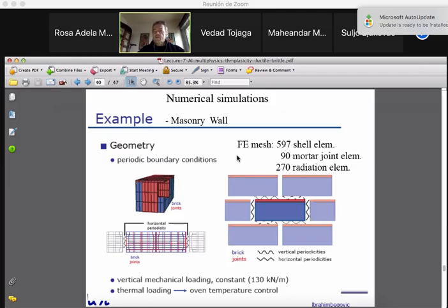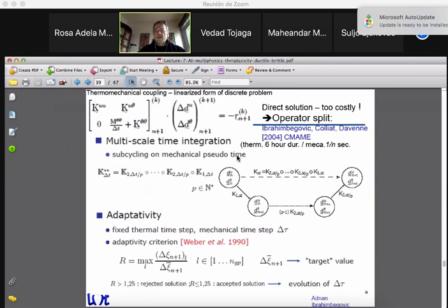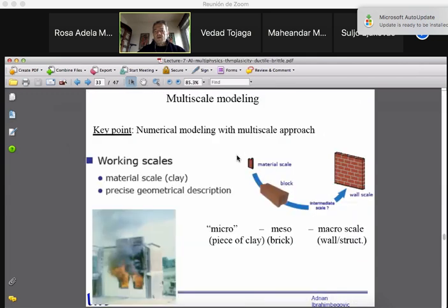So in those papers, we presented a simplified model. What is a simplified model? The wall is deforming in a very strange way. In other words, because of the fire, you have a curving of the wall around the horizontal and also in the vertical direction, and the one at the bottom is fixed. So basically, with this type of thing, you have a deformation which is three-dimensional.